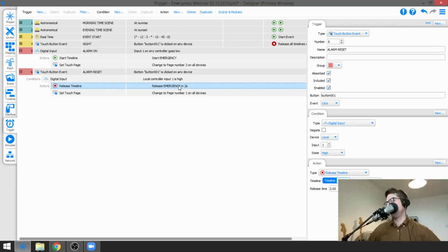Yeah, maybe to add to that, what we have seen happening is where the Pharos is connected behind the UPS. So even if the power fails, the controller will still run, but because it's connected to the UPS, it will receive a trigger from the UPS when the mains power goes away, and therefore it can start to dim the lighting, or it can turn some lighting off, by sending out other DMX values.